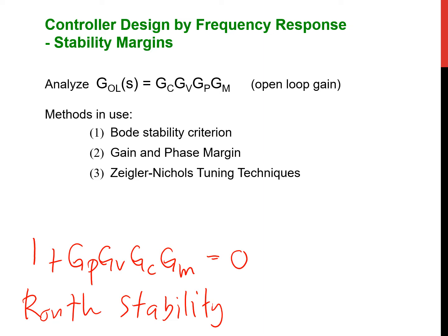So you develop the Routh array, and then you put the coefficient on each row, then you classify it on the first column, as long as it is greater than 0, must be positive. So if the first column is positive, then you will have a stable process. That one is based on the Routh stability.